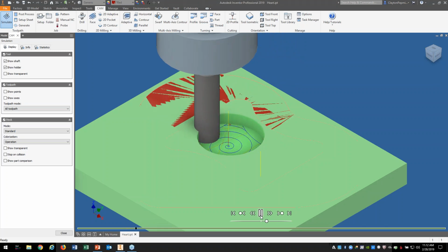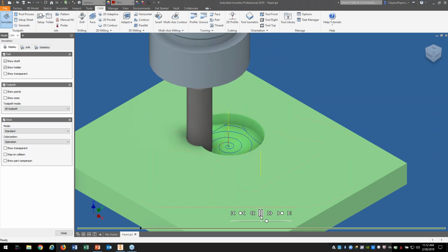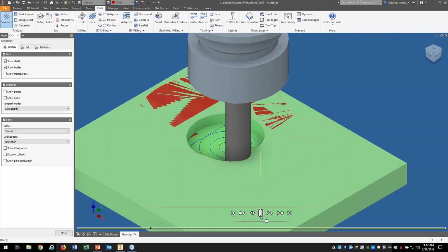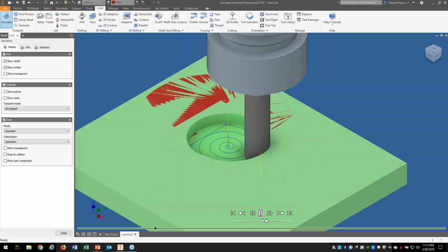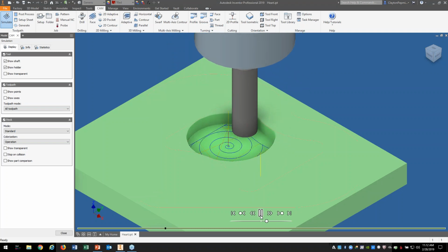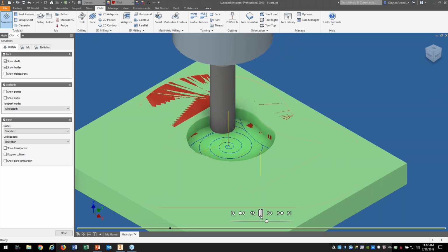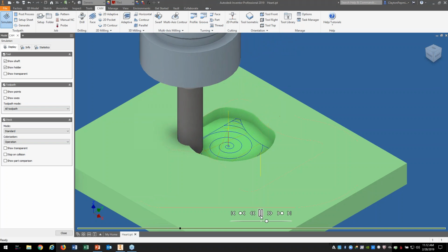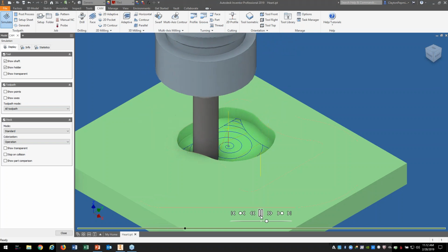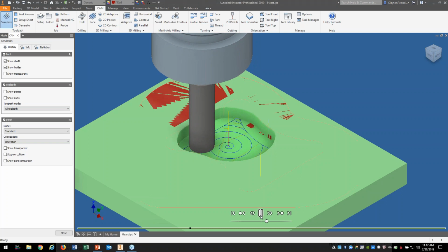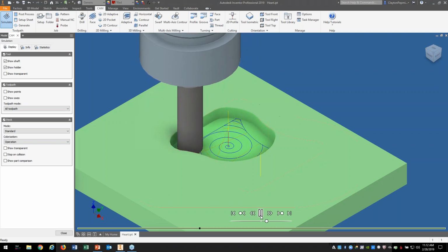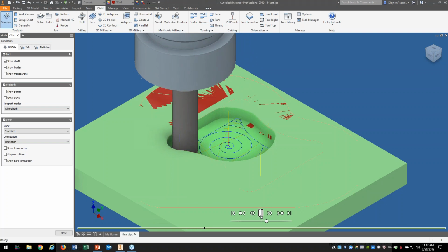Never cutting more than 25 or 50% of that tool, never cutting more than 1/4 of an inch. As it actually hits the sidewall, you can see it kind of avoid that sidewall. Again, you don't want to gouge your part, obviously. But as it gets into these corners, you can watch the entire tool path, and it never takes more than half of that tool. When it gets down to where it's got to dig in a little deeper, again, never more than half of that tool.